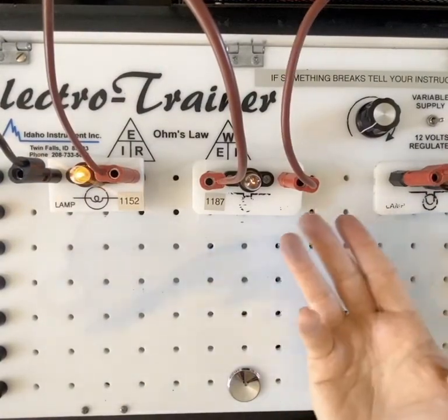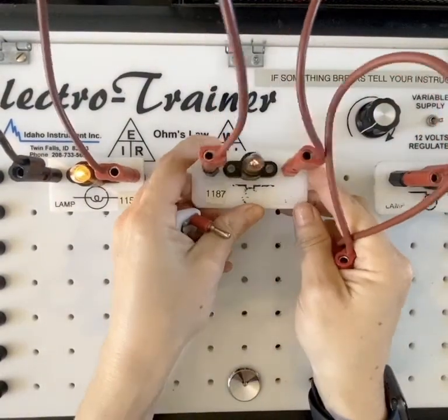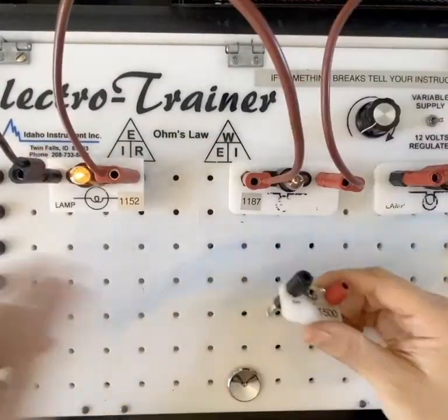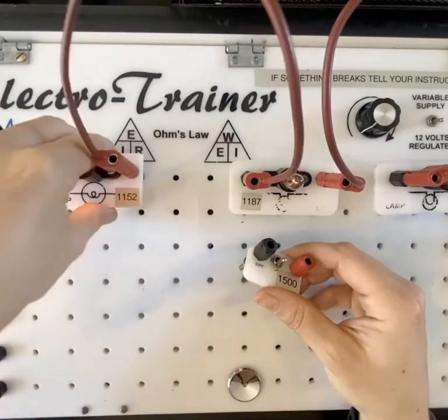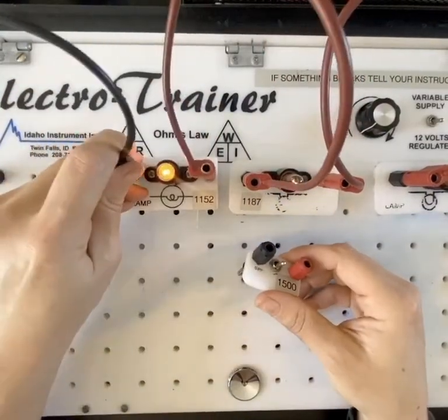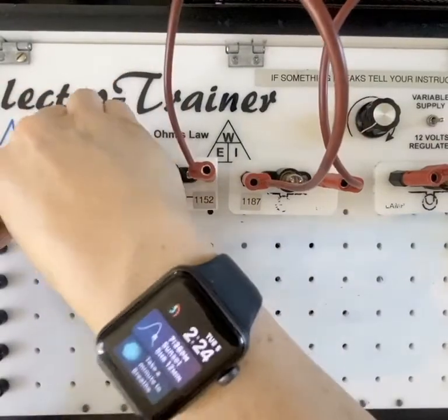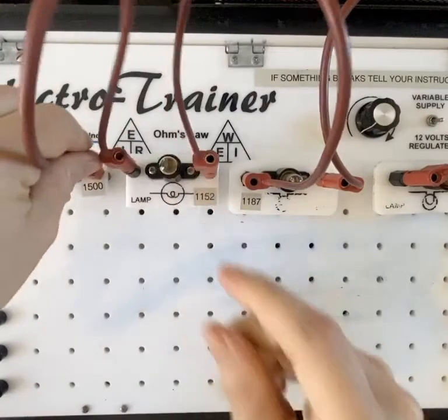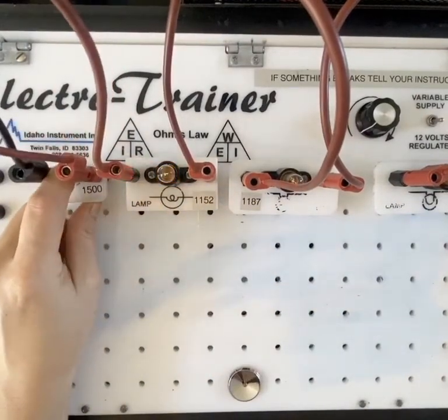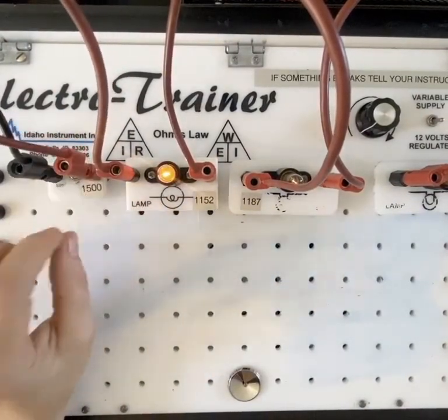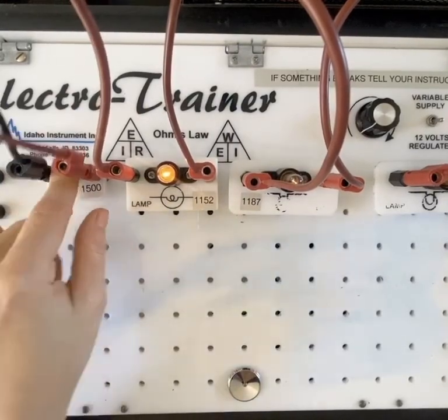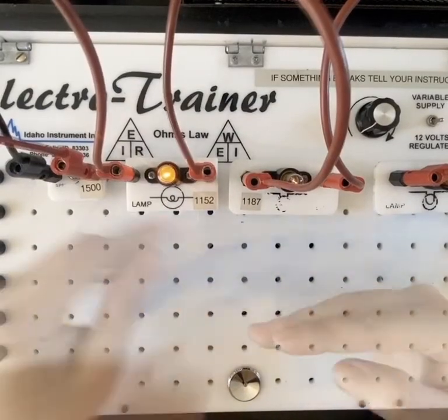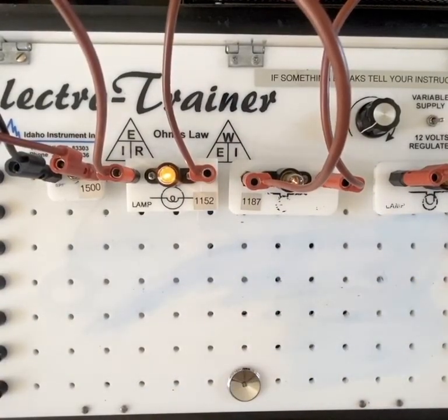Now, of course, I have no control. It's on all the time. But I can take my switch, I can put it in between light bulbs if I want to. I can put the switch at the end, at the beginning of the circuit. So I'll go ahead and disconnect this here. I'll put my switch at the end of the circuit, and we can see no matter what, I still have control, because all we're doing is creating a controlled open. No continuity, continuity. So that is how our series circuits work.